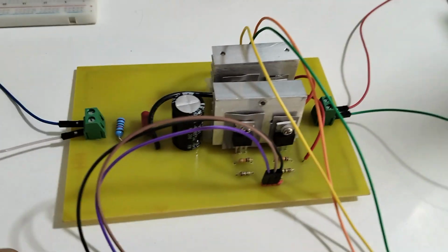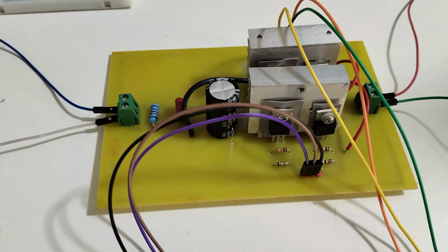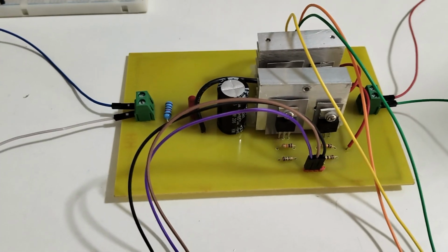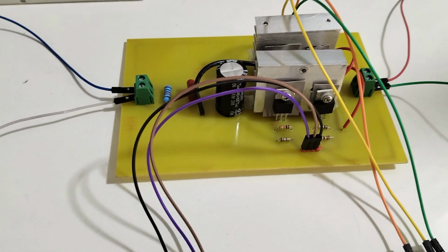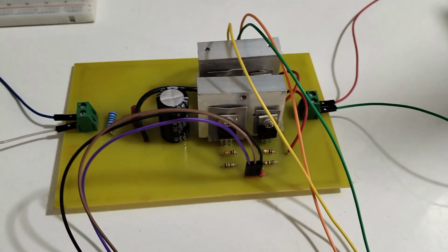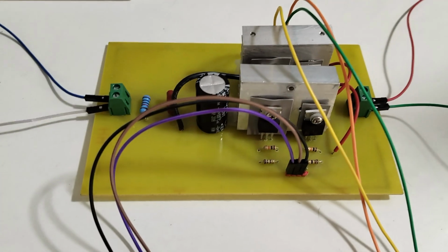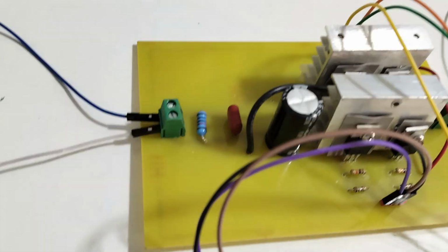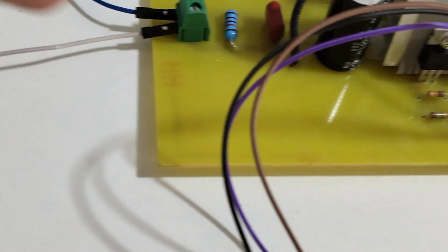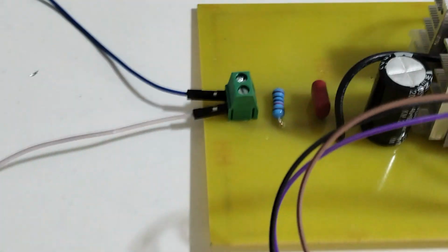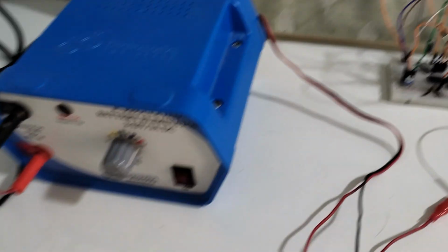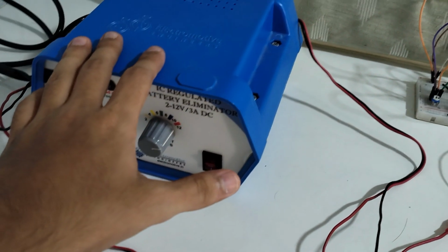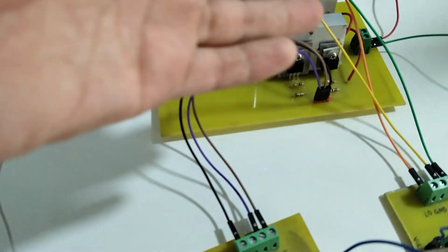I basically made an H-bridge PCB, since again putting this on a breadboard was becoming a hassle, and all the breadboard parasitics were really messing with the circuit. So I designed a PCB, and I etched it. We're just going roughly through it. On this side, the screw terminal is our supply input. I'm getting it from the supply, and the gate drivers, and this supply is for the power circuit, the actual inverter.